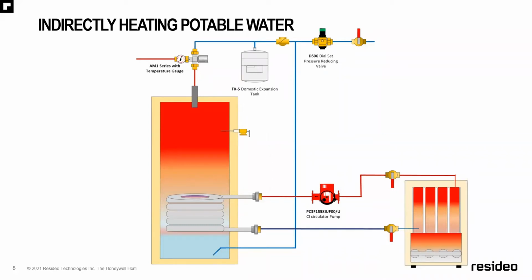Now I will say, if you do have a high efficient system, you're probably going to ramp up and use the higher capacity to heat this tank. When you have this type of system in a space heating application, you have a control that we also supply. It's a boiler controller, HPSR or HPZC system, that will prioritize the demand for the tank. The reason you want to do that is because you want the hot water right away, and you're not going to see the change in comfort while your boiler is prioritizing the tank.